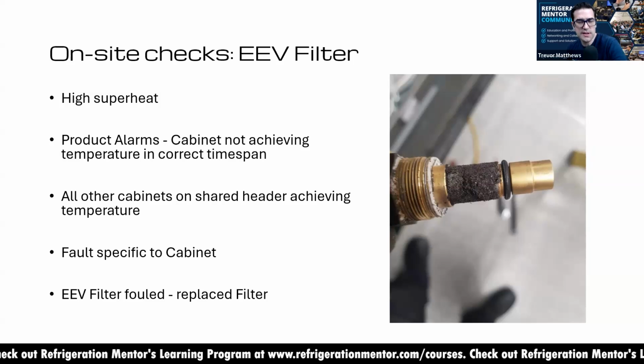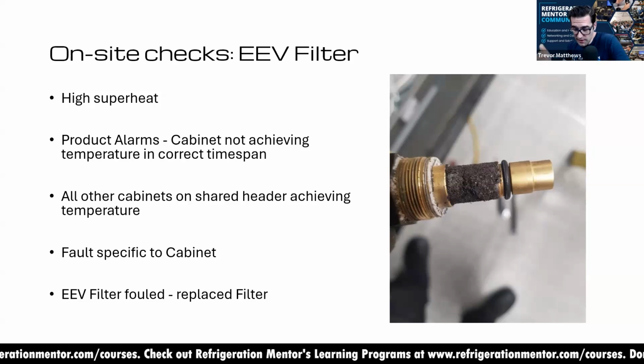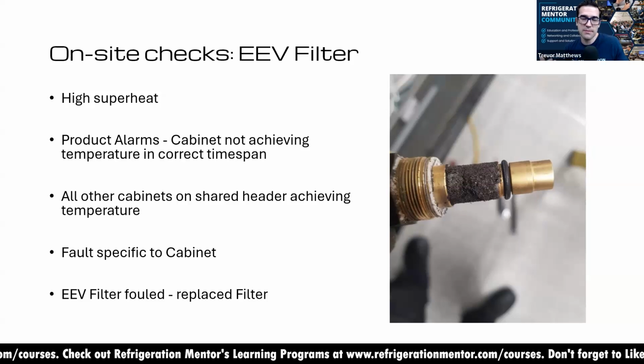that all the trees are dead around it now? All the grass is dead around it. And he told the group, he told all the other technicians, he said, Trevor, it's not the releasing of the CO2. It's the oil that may be in that CO2 that you're releasing out. And so this is why in my trainings, I'm like, get a recovery unit, put it in. And I know it doesn't have, because when I started out in the field, it was a different time.